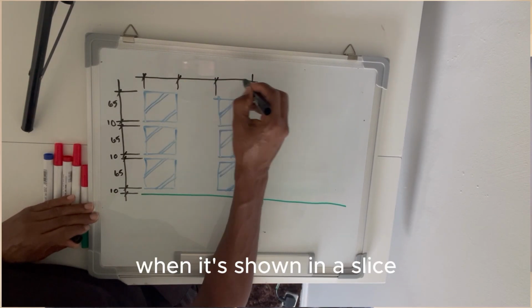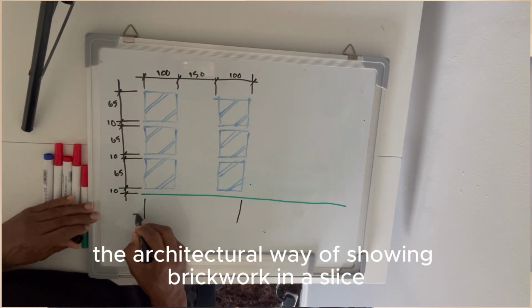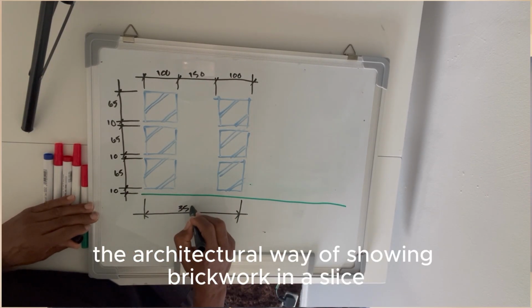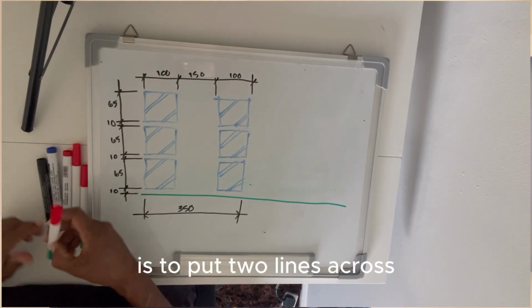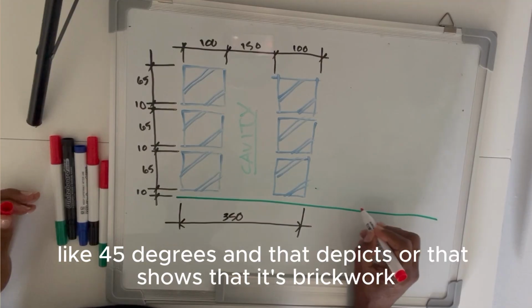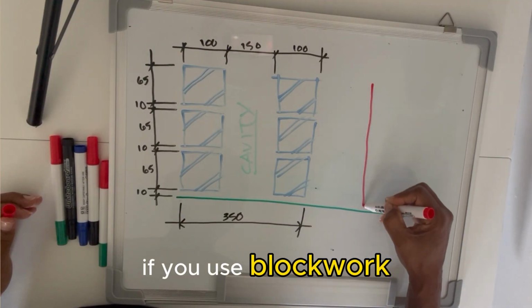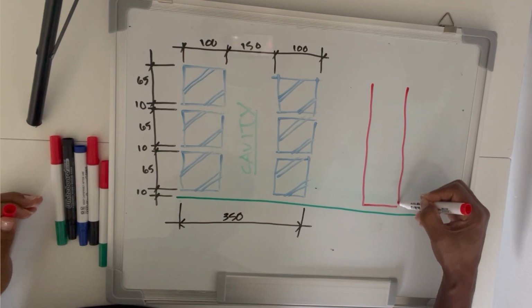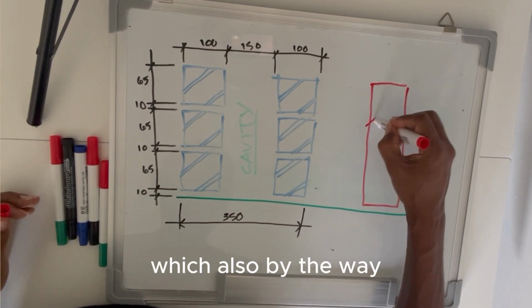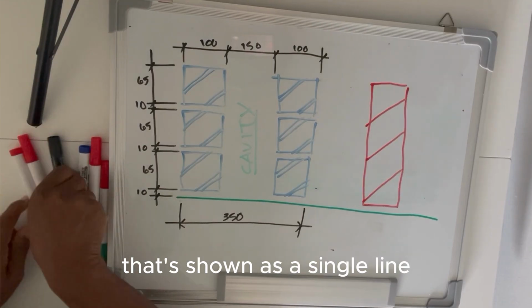And that's mortar. When it's shown in a slice, the architectural way of showing brickwork in a slice is to put two lines across like 45 degrees. And that shows that it's brickwork. If you use blockwork, which also, by the way, coordinates with brick, that's shown as a single line.